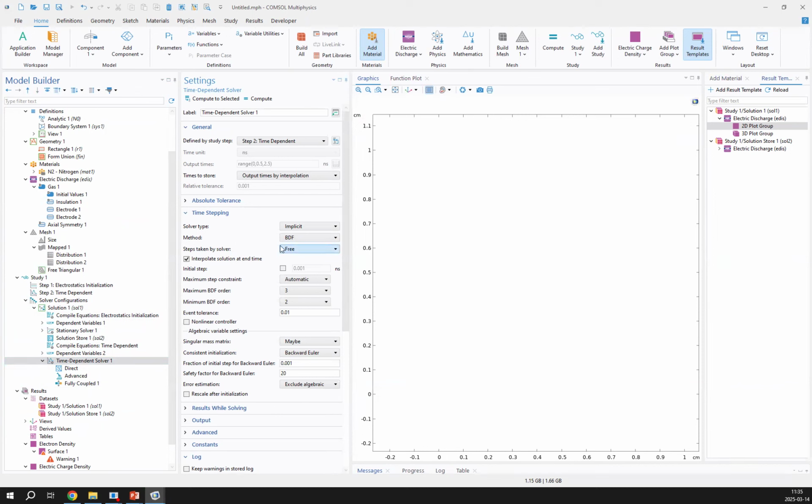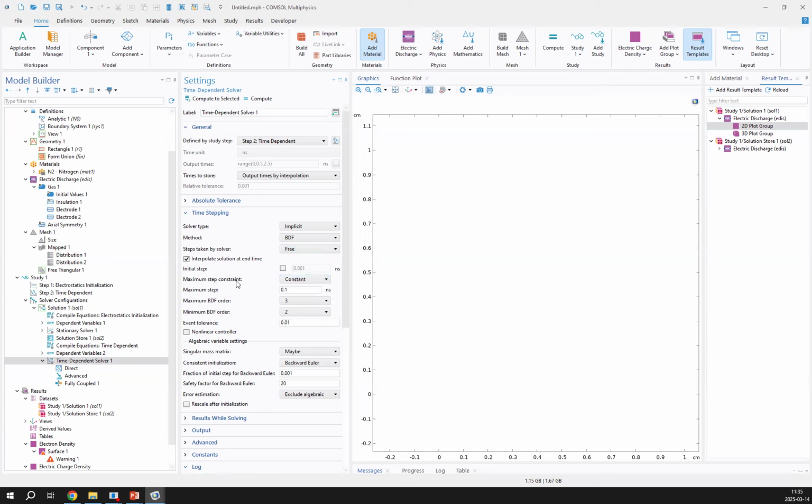As you can see, by default it uses adaptive time stepping, and the maximum and minimum steps are going to be defined based on tolerances and mesh parameters, but our idea is to limit the maximum time steps taken so that we won't skip any important dynamics of our streamer discharge. So I'm gonna limit the maximum step to 1 to the power of -11.